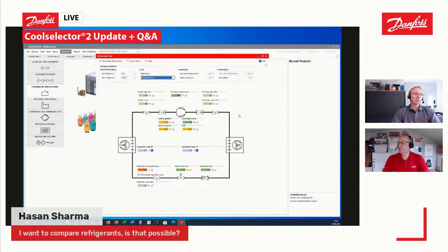So with that tool, you can compare two refrigerants purely on their thermodynamic properties. That you need to bear in mind. If you get a difference here for the compressor, for instance, it doesn't necessarily mean you get the same difference if you compare two compressors which are optimized for the individual refrigerant.